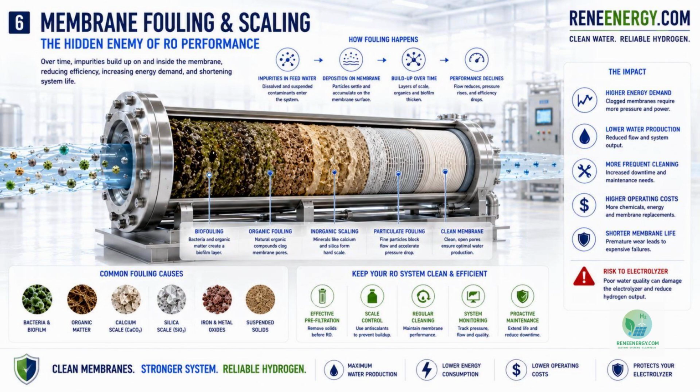As fouling grows, the system must work harder to push water through the membrane. That means higher pressure, higher energy demand, lower water production, more cleaning, more downtime, and shorter membrane life. This image is important because it reveals that RO performance is not fixed. It degrades if the system is not properly protected, monitored, and maintained.